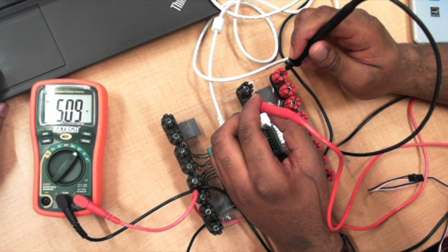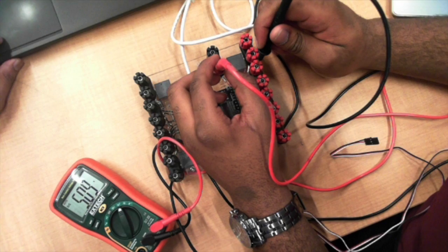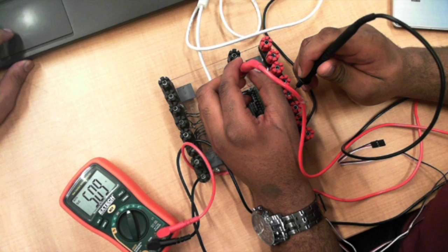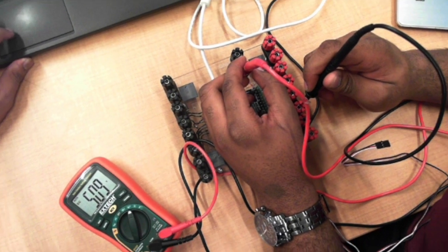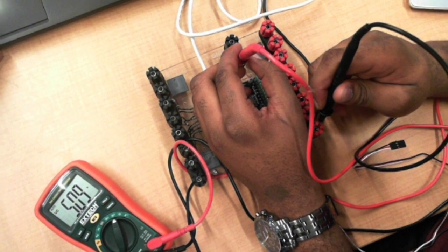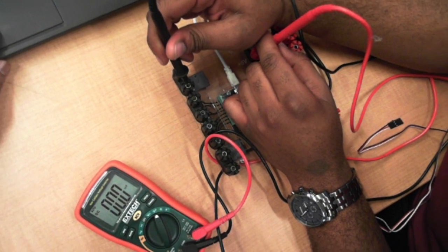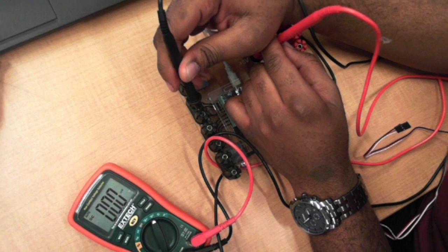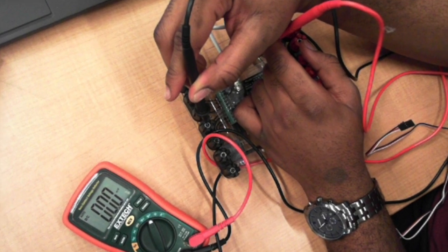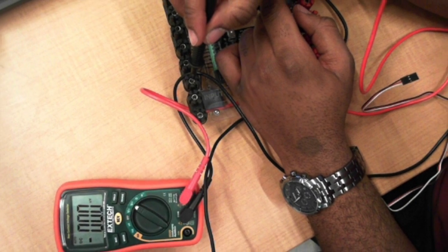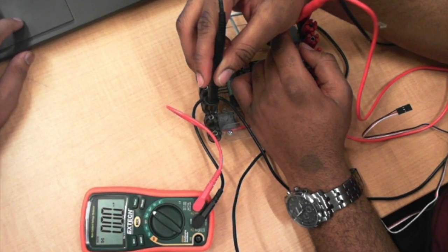Using a similar setup from step number 2, we began on step number 3 where we measured the voltage for each of the 8 digital outputs of the board and verified that none of them are active, since we got 5 volts for each, as you can clearly see. Similar to step number 3, we began step number 4 in which we measured the voltage of each of the 8 digital inputs and verified that none of them are active, since we got a value of 0, as you can clearly see.